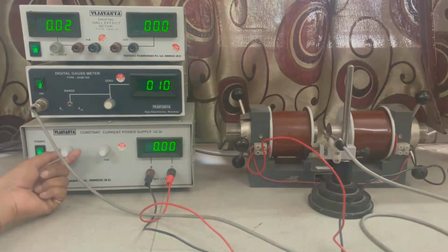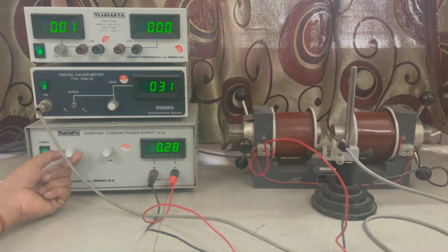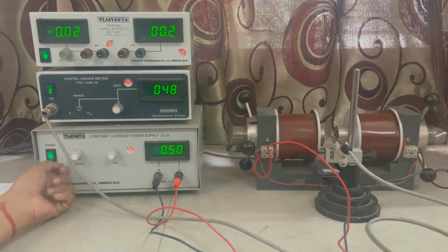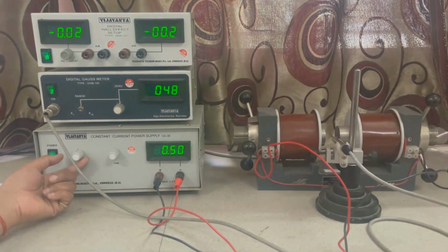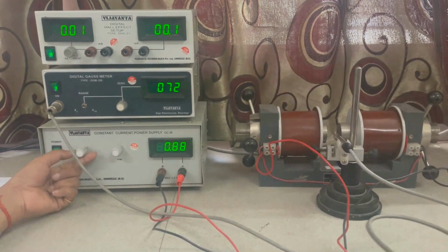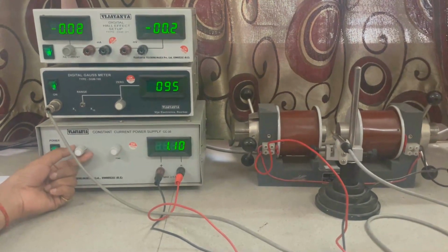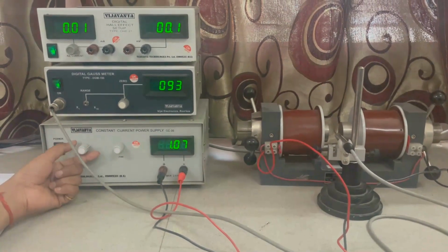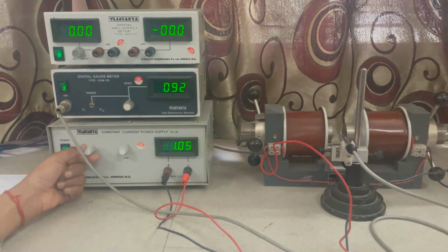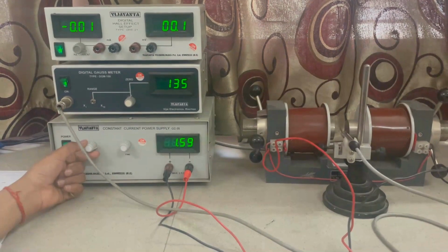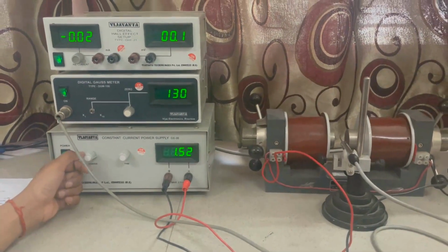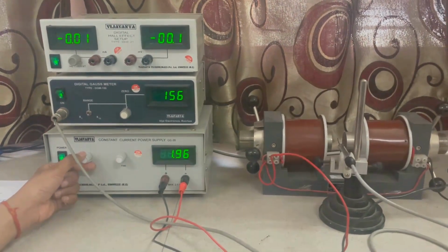We have to first calibrate the amount of current applied and the magnetic field, because we cannot directly change the magnetic field. We are changing the current, and that is changing the magnetic field. So first we need to get this relation between the constant current applied and the magnetic field. The Gauss probe has been kept between the north and the south poles, and as I'm changing the current, the reading of the Gauss meter is changing. As I'm increasing the current, the magnetic field is also increasing. So the first reading that we have to take is between the constant current applied and the magnetic field generated.